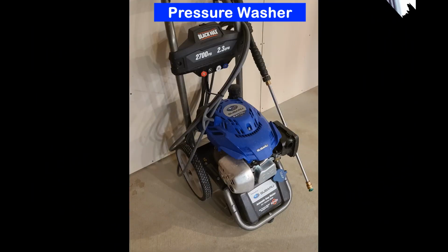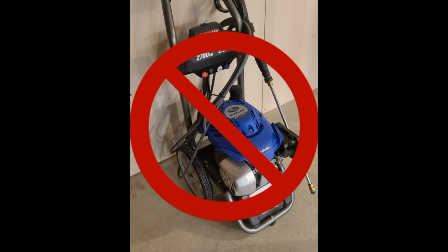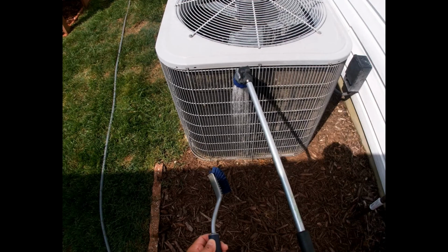The solution to this problem is to simply clean your condenser coils 2 or 3 times a year. However, it's important you clean it properly. I strongly recommend against using a motorized pressure washer because its powerful stream of water will bend your condenser's delicate aluminum fins, which will also restrict your cooling air through your condenser. I recommend that you use a standard garden hose and possibly a brush with very soft bristles.